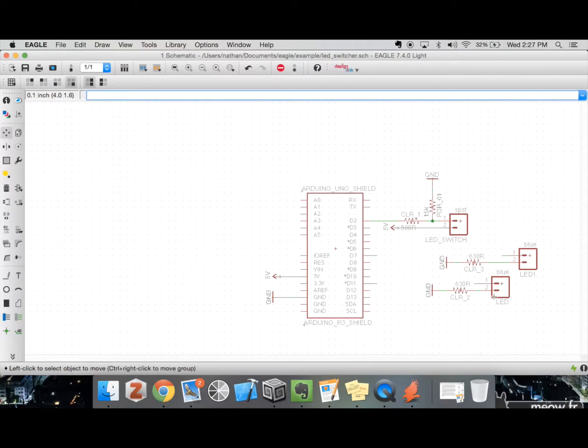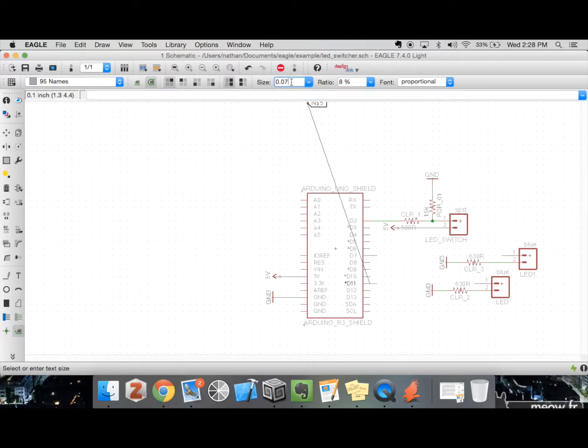Okay, wonderful. And then I can use the label tool down here to give myself a label for these nets. I'm right-clicking to rotate it, and it gives you by default these lettering styles, which I find very ugly and terrible, so I changed it to flags. At 0.7 you'll run into trouble because they won't fit right next to each other, so I tend to bring it down to 0.4, which will give you enough space to have multiple lines of these.